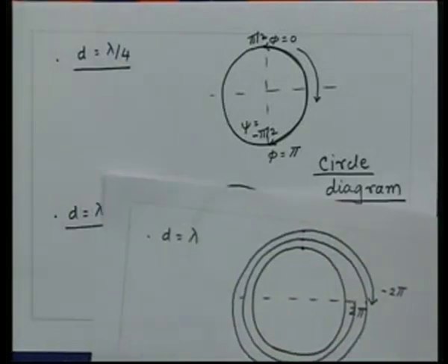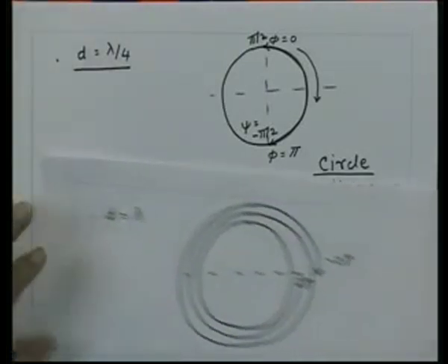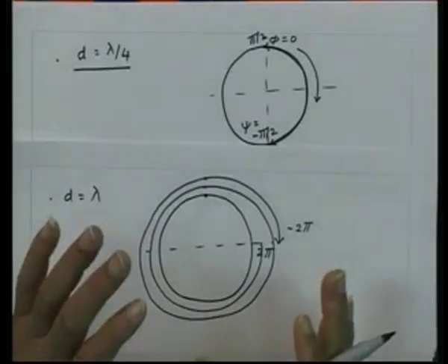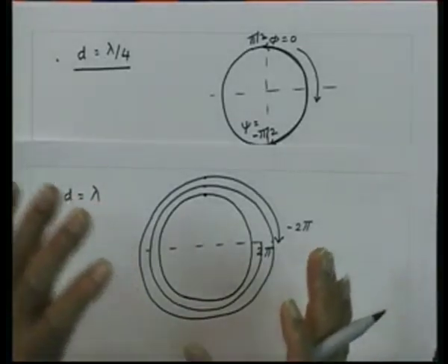The circle diagram essentially is the visualization of the roots of the polynomial on the unit circle, or in general on the complex z plane, to see whether these nulls would correspond to the physical nulls in the radiation pattern or not. Once you understand this, then synthesizing an array which is specified by their nulls is very straightforward.